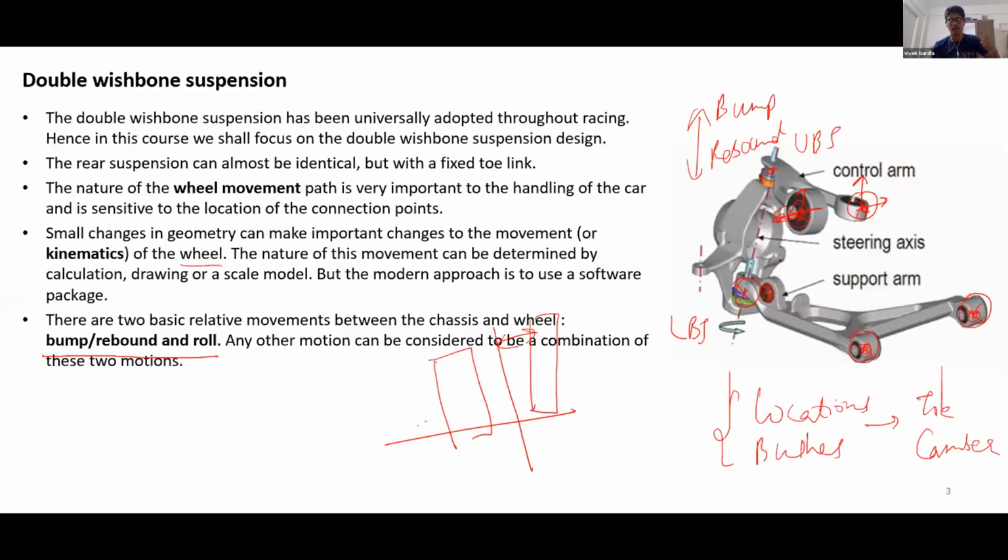Because the hinge, or I think what you're trying to say is the bracket on which the LCA or UCA is mounted, depends on how much load or how much forces the LCA and UCA resist, right? Generally, the LCA or the lower control arm resists a higher amount of forces. So they are generally sturdier than the UCA, which is more for kinematic purposes and hence can be lighter. So this is why the construction of the LCA and UCA hinges are quite different.